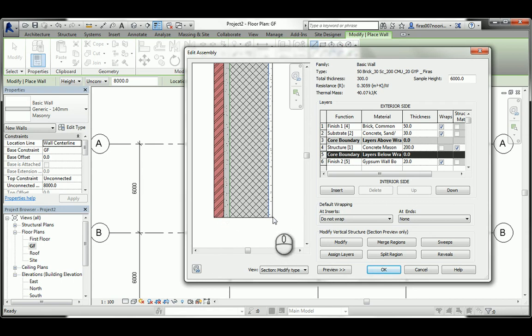So if you depend on wall center, the wall center will be here, while the core center will be here. That's really important to distinguish between them. So for the wall center line, you ignore whatever is inside, take this point to this point, and divide it by 2 to get somewhere here, while the core center line is exactly at this point. So it's in the middle of the distance between this core boundary and this core boundary.